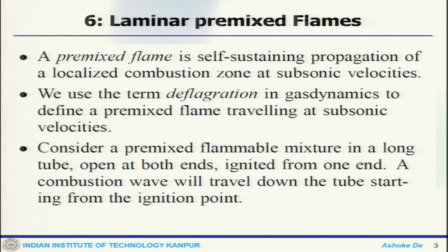Now, there are certain important properties that one has to know before getting into the details of these premixed flames. One is that the premixed flame is the self sustaining propagation of a localized combustion zone at subsonic velocities. This is an important point. Sometimes we call it deflagration in gas dynamics, or compressible gas dynamics, to define a premixed flame traveling at subsonic speed.